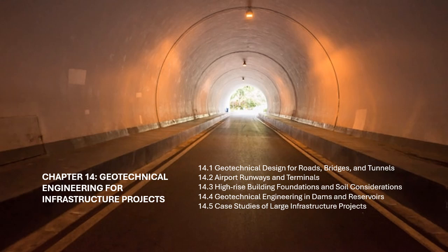Soil compaction and stabilization. The subgrade and pavement layers need to be adequately compacted to ensure that they provide sufficient load-bearing capacity and prevent future settlements. Geotechnical engineers use compaction tests, such as the Proctor compaction test, to determine the optimal moisture content and compaction work for the soil. In cases of weak or compressible soils, stabilization techniques, such as the use of geosynthetics or lime stabilization, may be employed to enhance soil strength and reduce settlement.